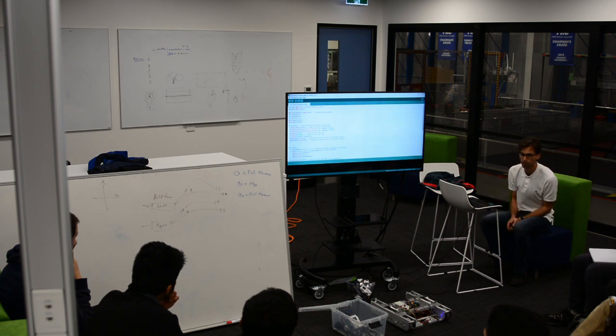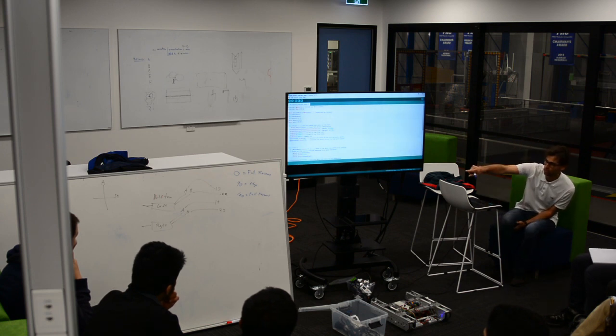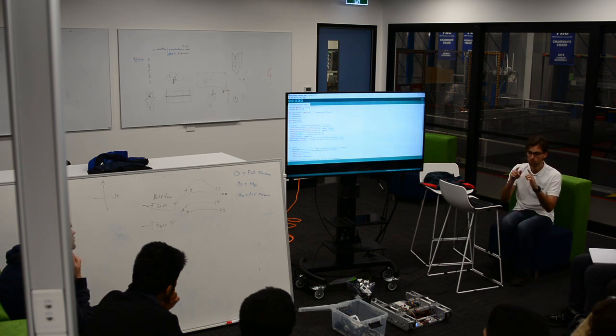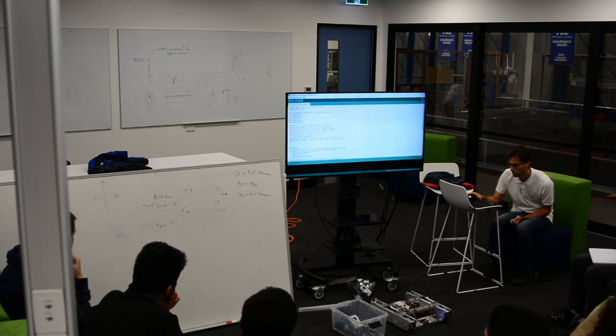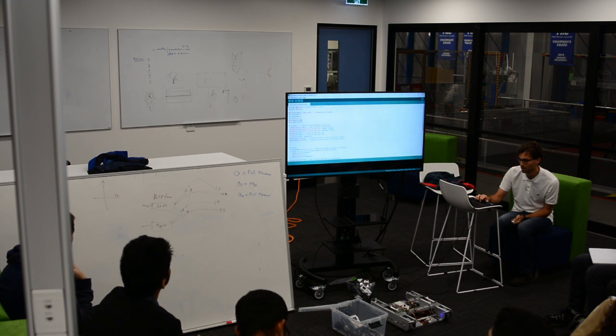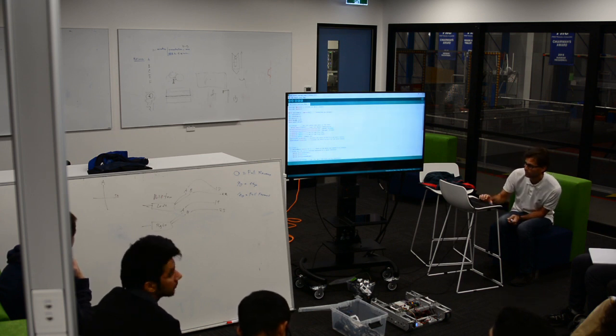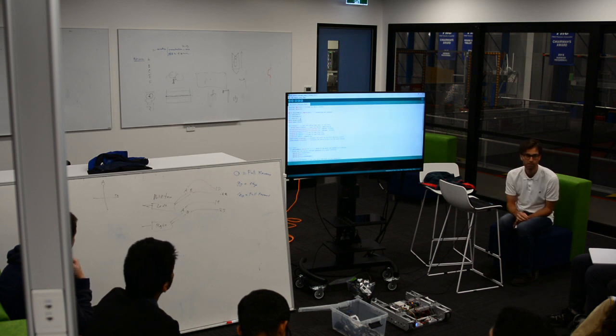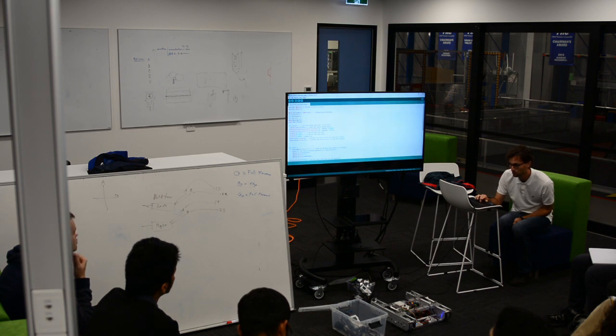Okay, so now I've included another library called servo.h, and it's the thing that's going to help us communicate with those white boxes by generating pulses of the right width corresponding to how much throttle we want to put out. I've still got my Metro, I've still got counts. I've introduced a variable called throttle. It's an integer, and I've done this. This servo command is something that is enabled through the servo library, and it sets up this thing called my servo left. It's a pointer. A pointer, okay. It sets up a pointer that has certain properties.